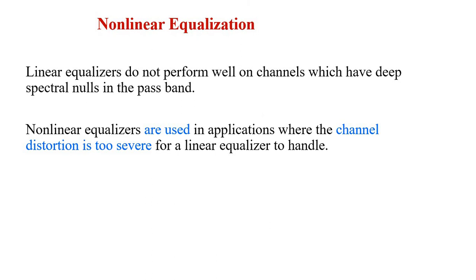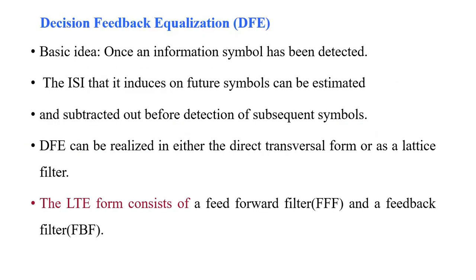So now coming to the non-linear equalization. In non-linear equalization, wherever we find that the distortions are heavy, that is, too much distortion, in those areas we can only go for the option of non-linear equalizers, because with the linear equalizer we cannot adjust the weights accordingly for the errors. The error bits will be too much, and that we need to adjust. So in that category we are going for non-linear equalizers, where we can see that much distortion is available.